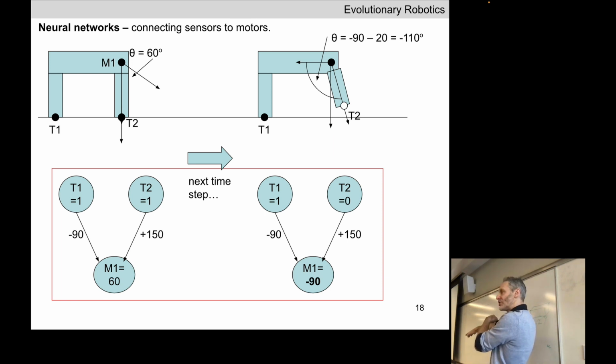I want to define the joint normal for this joint so that these 2 links are going to rotate through the horizontal xy plane. What's the joint normal that I need to define to cause these 2 links to rotate horizontally relative to one another? Like Z, 0, 0, 1, right?